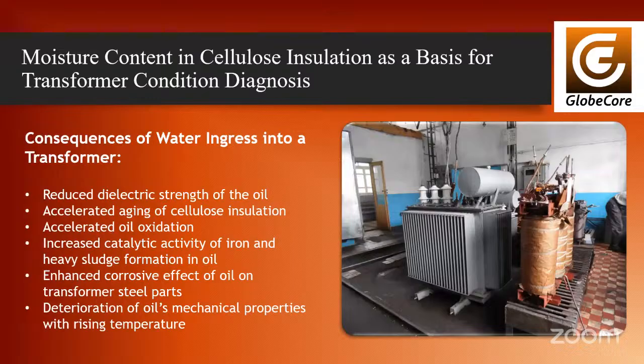Quicker oil oxidation. Stronger corrosion of steel parts inside the transformer. Weaker mechanical properties of oil when temperature rises.